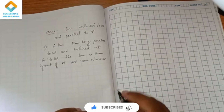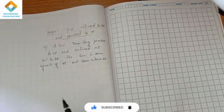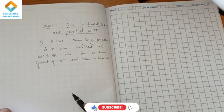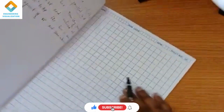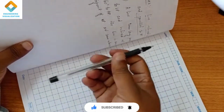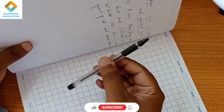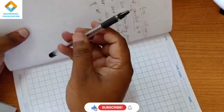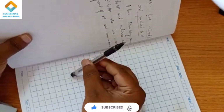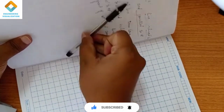See the fourth case in projection of line. The line is inclined to HP and parallel to VP. Here we have to give inclination to HP and make sure that the line is parallel to the VP. So how is it done? You see it here. This is the vertical plane, this is the horizontal plane. In this condition it is both parallel to HP and parallel to VP. Now I am going to give inclination like this. You can see here, this is parallel to the VP, but here it is the inclination from the HP plane. It is inclined to the HP and parallel to the VP.